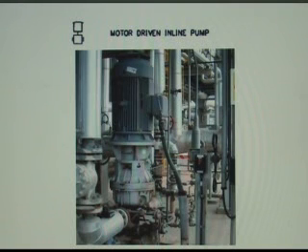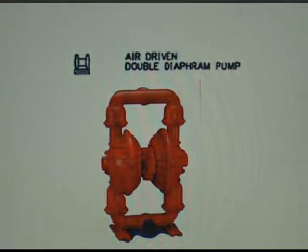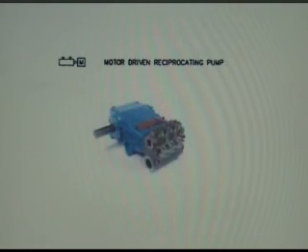As the pipes move because of thermal growth or other strains, the pump follows it around, so it'll physically slide around. So it has to have flexible connections for the electrical system, and anything that it can't have flexible connections for has to be physically mounted on the pump itself someplace. Air-driven double diaphragm style pumps. This one is good for relatively low flows and low heads, but as a sump pump, they're stupendous. Motor-driven reciprocating pumps. You'd have the motor out here connected to the drive shaft. The pistons are in this area here, and then the actual pumping takes place here.